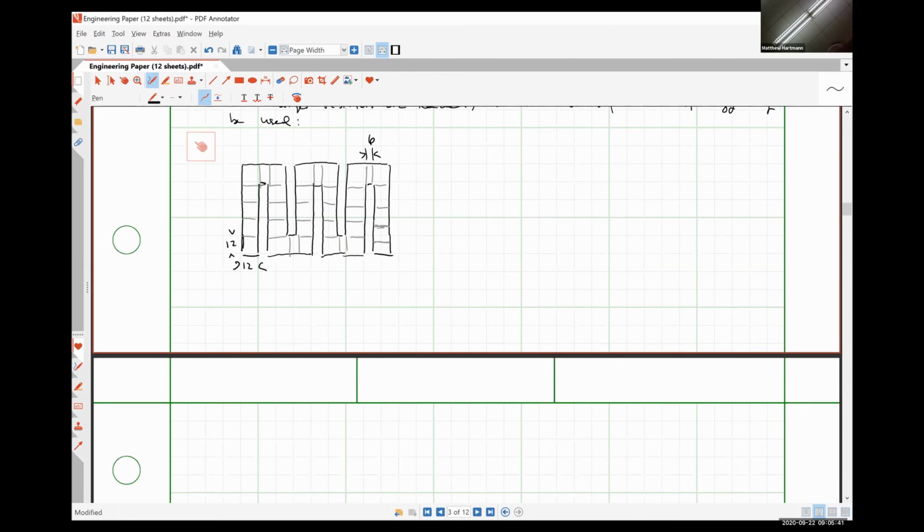So what we've done is we've minimized the footprint of a larger resistor. Instead of stretching out to be one really, really long resistor, we've used probably actually more area per se, but we don't have to have nearly as long lengths of free space.